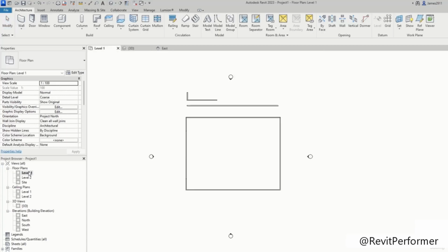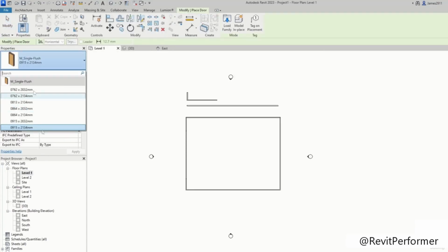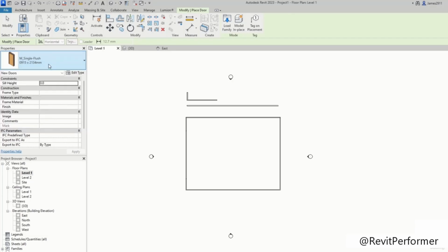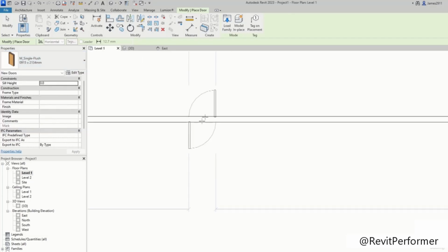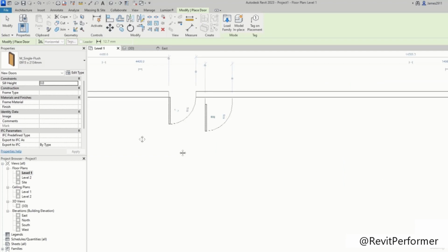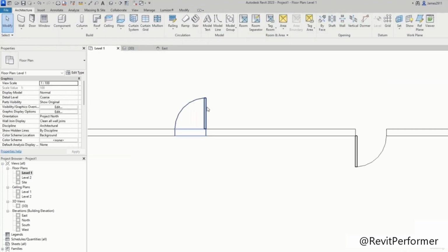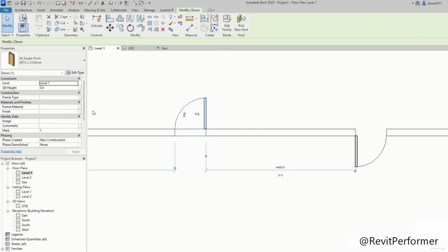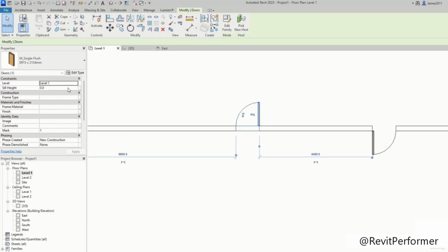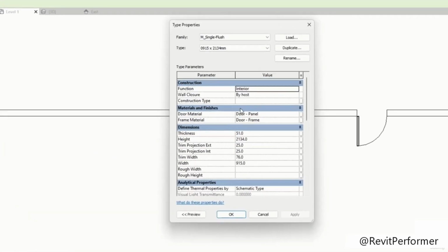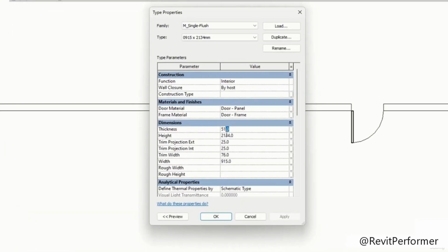Okay, so today we're going to have a look at doors and windows. How do we add doors to our walls? Simply, we go to level 1, we click on the door option. We have a couple of examples here. Now I can simply go in my wall and click here. This will add a door to our wall. We can also change the door types. We have a couple of types we can edit. We can also change the door thickness, the height, and other stuff.